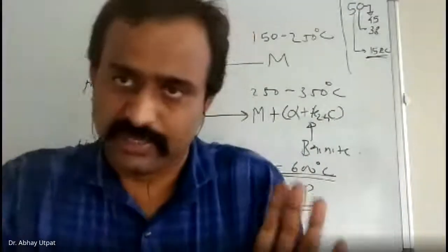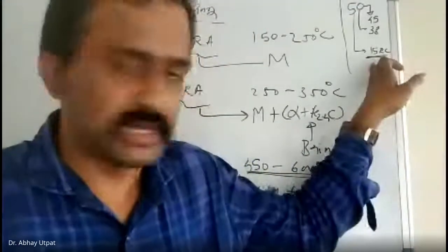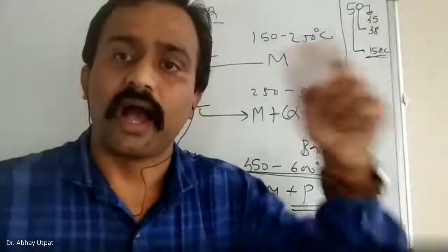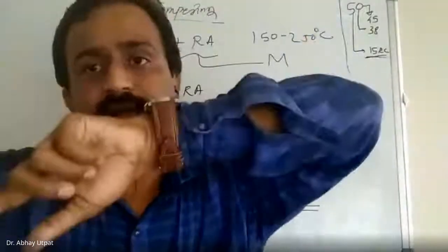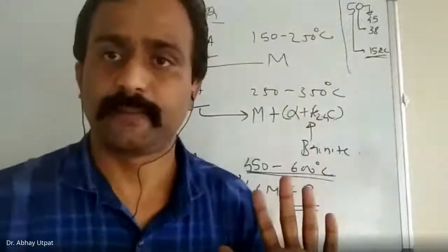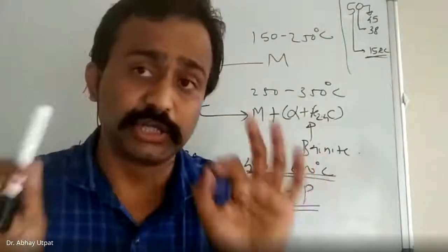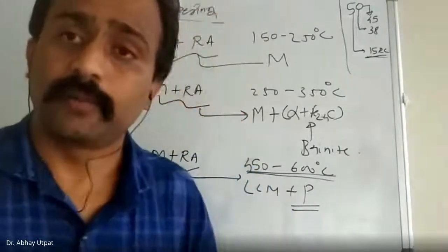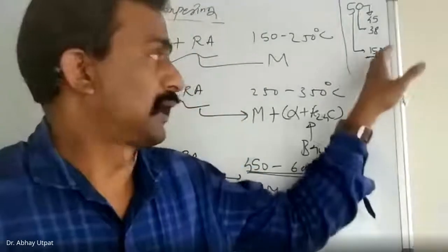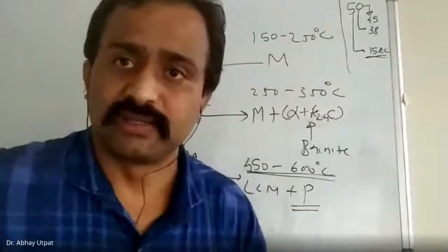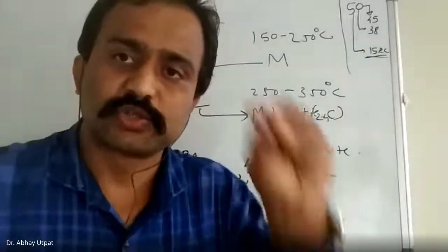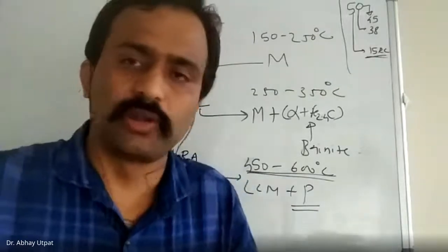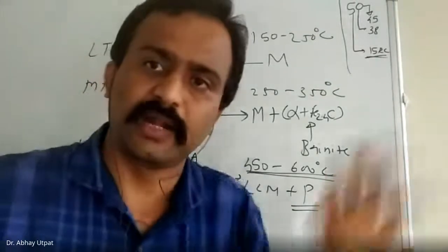If a simple treatment gives this hardness, why go for hardening and tempering to achieve it? Very interesting, this is an interview question. Write it somewhere. Even normalizing gives around 15 to 20 RC just by heating, soaking, and cooling in air. It is a low cost process, no cooling media is required, you can keep it in the atmosphere.